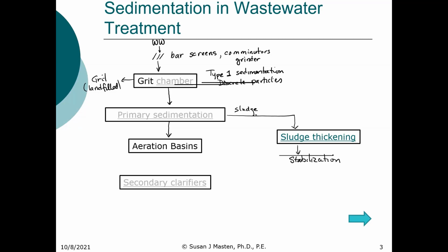In some cases, stabilization can be digestion, where you're using microorganisms to react that organic matter, consume that organic matter, and typically you're looking at producing CO2 and methane. Stabilization can also be incineration, where we're not obtaining any useful energy from the material.